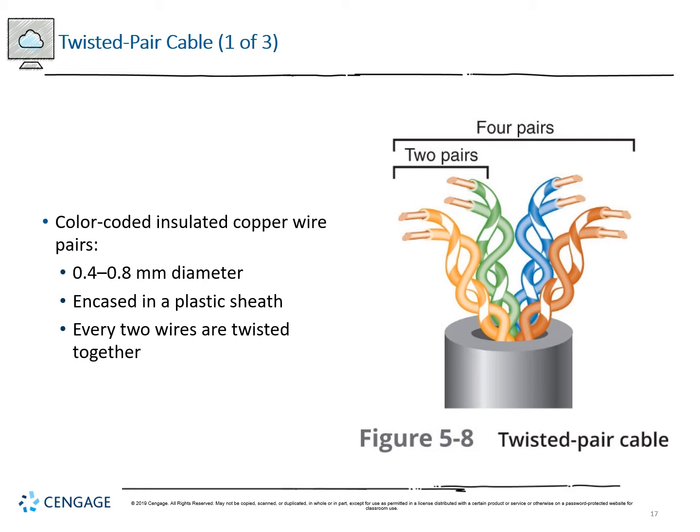The idea is that when we talk about cables running parallel to each other and causing interference, we instead want to twist them together so that each point, depending on the tightness of the twist, they're actually running perpendicular to each other. So if we look at figure 5.8 very closely, let me grab my laser pointer and we will take a peek there. If we look right here, we can see that there is a point at which the cables are running in an X shape.